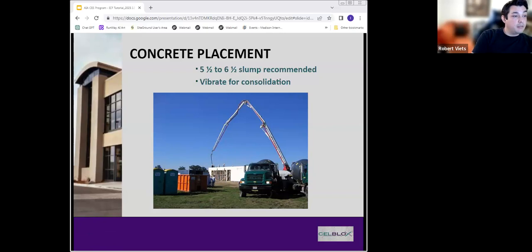One cooler thing about an ICF wall is you can use lower strength concretes because of the insulation of the ICF wall containing the moisture of the concrete. The concrete actually cures slower than an open air cure. Since it cures slower, it actually cures to a stronger PSI rating than normal. So if your structural engineer says so, you can get away with purchasing less expensive concrete mixes or slag concrete mixes.